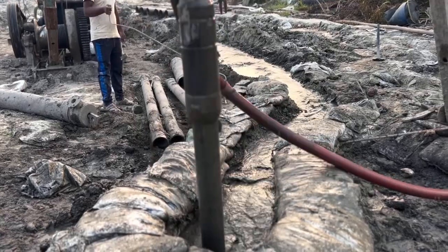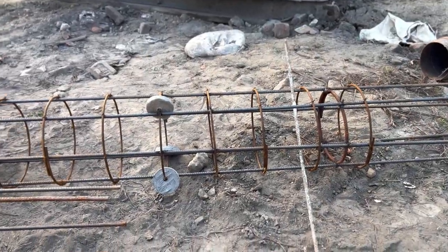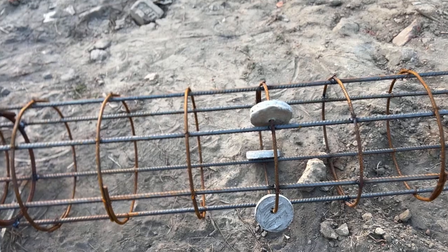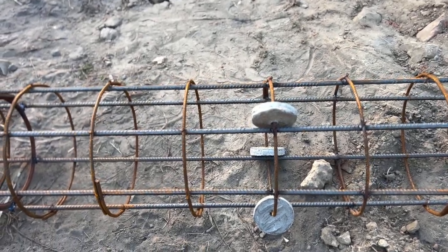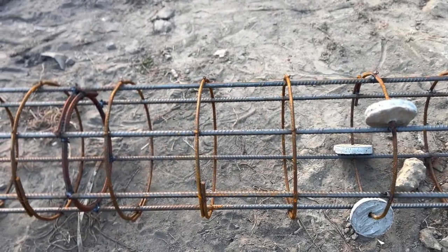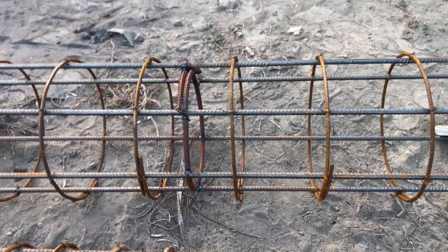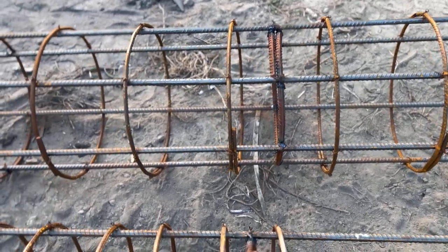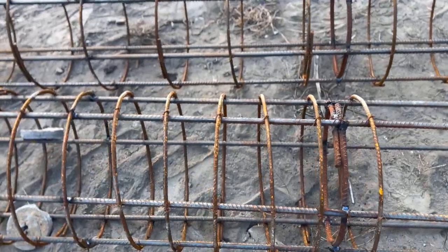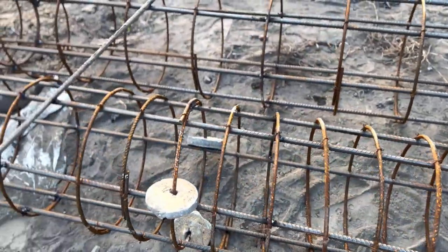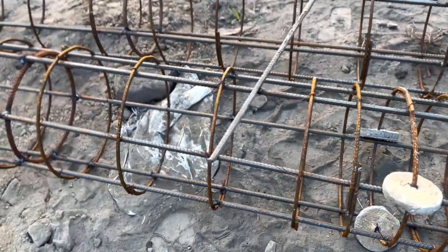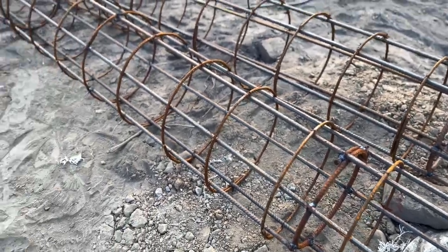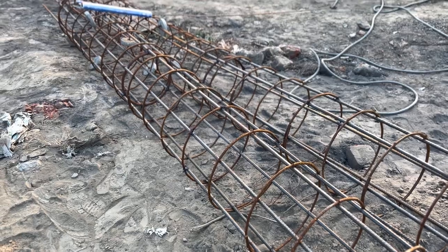The next is, what are the equipment and tools required. See, it cannot be done by a single person. It is a specialized work, so that is why we need specialized types of equipment. So what equipment do we need for the DMC bore pile? First, we need the rotary drilling rig to create the borehole by rotating a drill bit. That means we need to create a hole inside the earth. To create that hole, we need the rotary drilling rig.